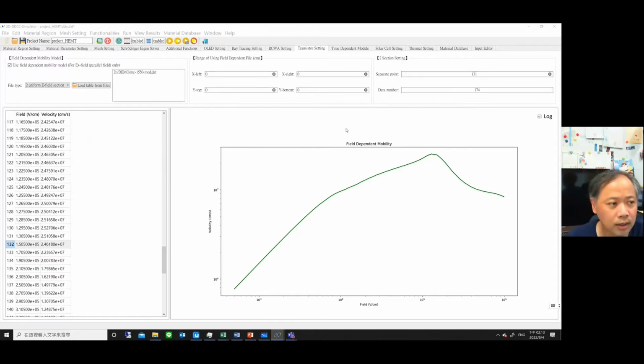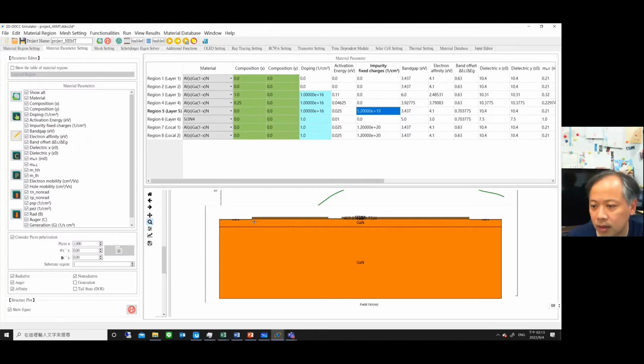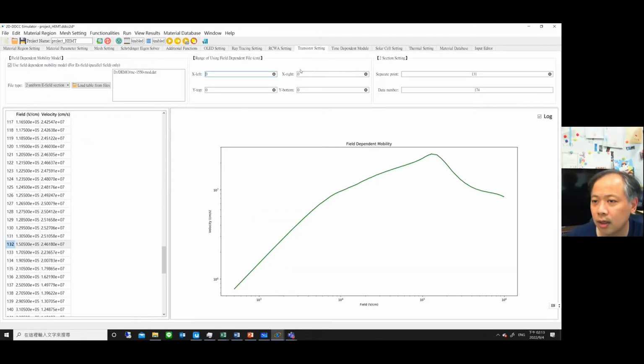And there's another, the channel region setting. So we know that the channel in the material is from here to here. So we can set up the channel. The channel we are going to set is 2.499 E minus 5. That's the starting point, 0.25 micron, and to 1.95 E minus 4, 1.5.